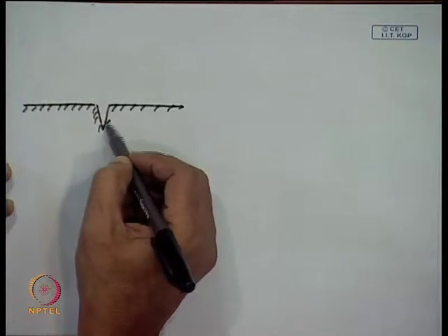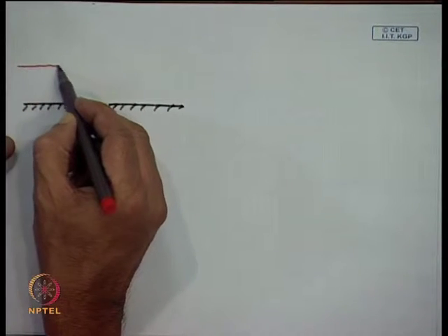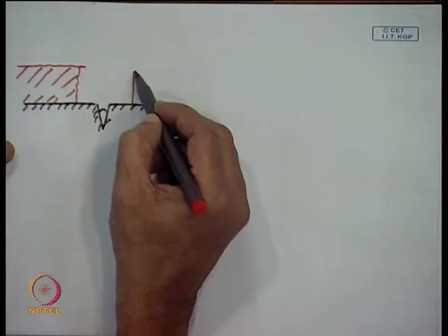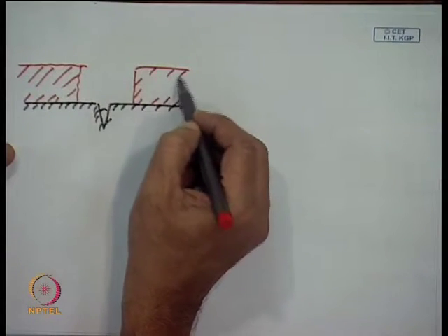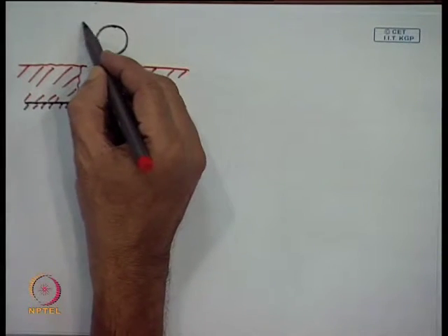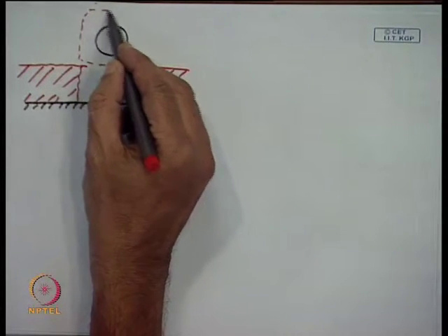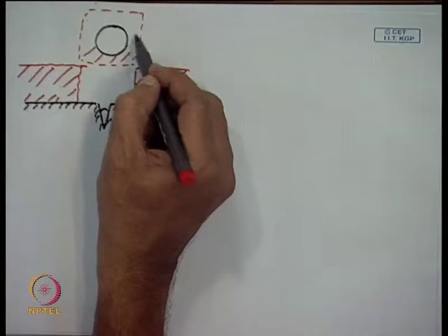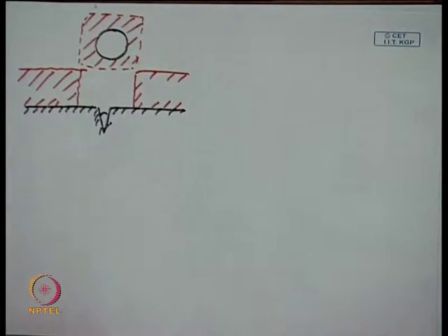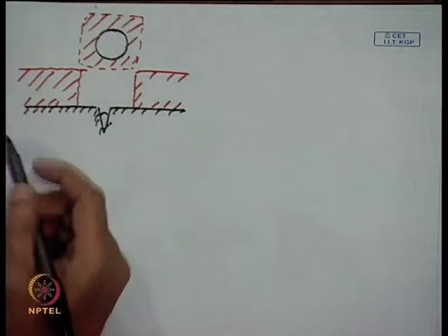This is a solid surface, and we have, as I have told, a thermal boundary layer. So, this is the heated liquid, and what happened is that a bubble has already departed this surface. When it departed, it took this much amount of heated liquid along with it. So, we can tell that this is our first phase.